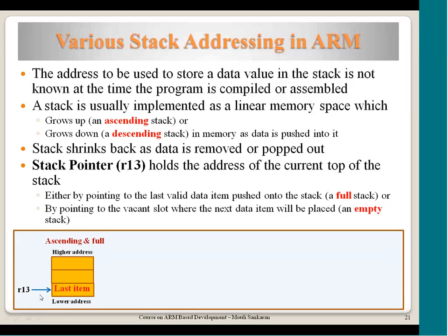That means the stack is growing in the ascending direction, that means towards a higher address, and the stack pointer is pointing at a location in the stack which is full, already filled with some item. Now when the next stack operation is done on this, we can imagine how it will move. It's ascending, so it has to move towards the higher address.